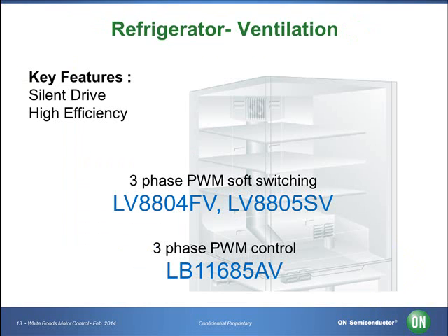In these types of application designs, it is important to be able to use highly efficient sensorless motor drivers that are easy to implement. The LV8804 and 8805 and the LB11685AV from ON Semiconductor are 3-phase drivers optimized for low power consumption and low vibration. These drivers do not require Hall sensors, enabling a reduction in the size of the motor.